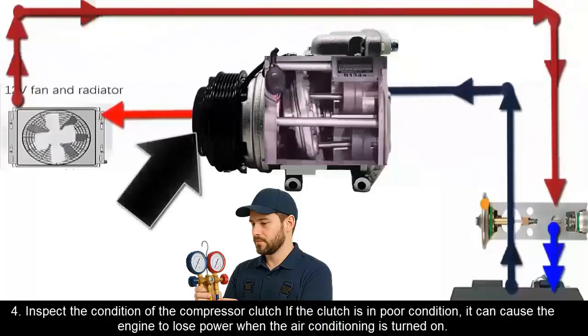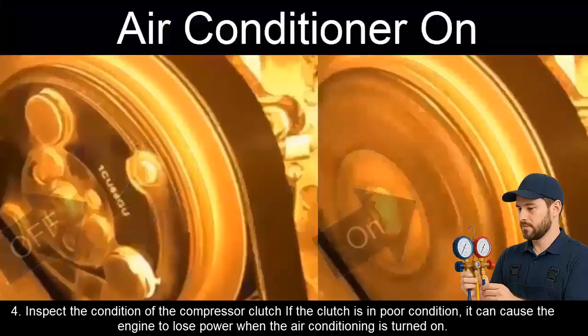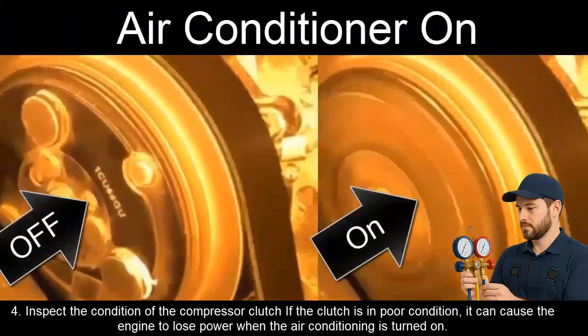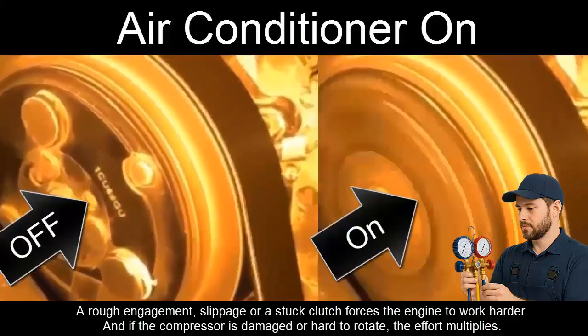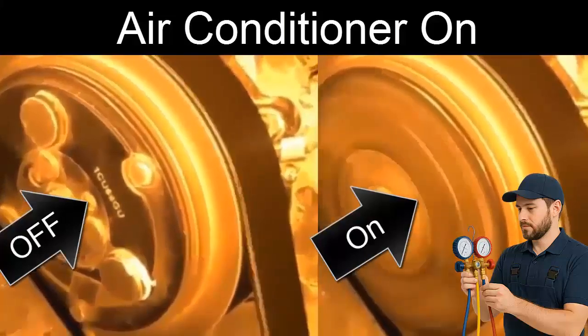4. Inspect the condition of the compressor clutch. If the clutch is in poor condition, it can cause the engine to lose power when the air conditioning is turned on. A rough engagement, slippage, or a stuck clutch forces the engine to work harder. And if the compressor is damaged or hard to rotate, the effort multiplies.